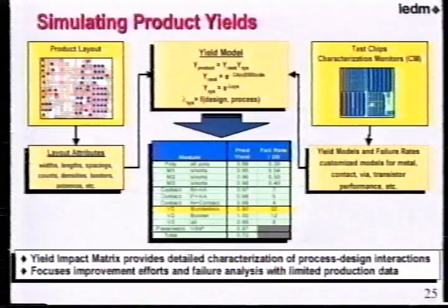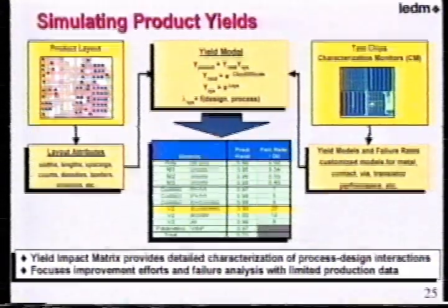Here it's showing that there's 20 parts per billion fault, and there's enough number of borderless vias that I do see a significant yield loss. We're talking about a single layer of via giving a 10% yield loss right off the bat. Okay? If this was not an issue, that is, if I didn't have enough vias out here, this would have shown up to be 0.99 or 1.0, then it's not a problem. Yes, borderless vias are not great, but you know what? For this product, it's fine. So this drives the focus, or the Pareto, by which you should be fixing problems.